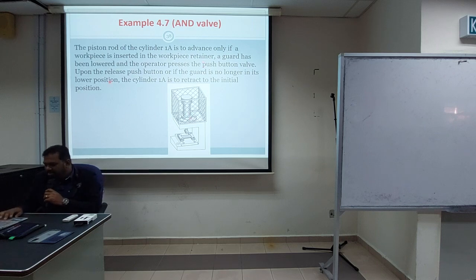So all using a roller valve, and then push the button, then it will turn on to extend. So if one of the conditions is not met, you don't extend the cylinder. Upon the release of the push button, or if the guard is no longer in the lower position,